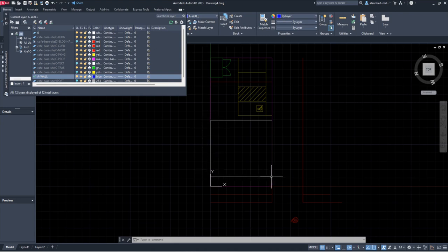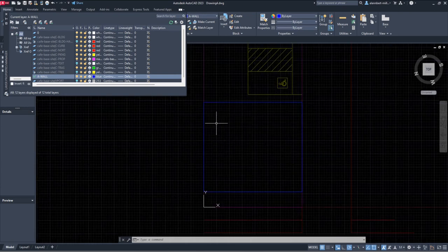So what I'm going to do now is trace over this box. So I'm going to type in a rectangle, REC for rectangle. And then I'm simply going to click here and then click there, right? This is now the outline of my building, just like I was planning on doing. A rectangle creates a box that's one piece. I don't want it to be one piece, so I'm going to type in explode, okay? And then I'm going to select that rectangle. Now they're different lines altogether, okay?